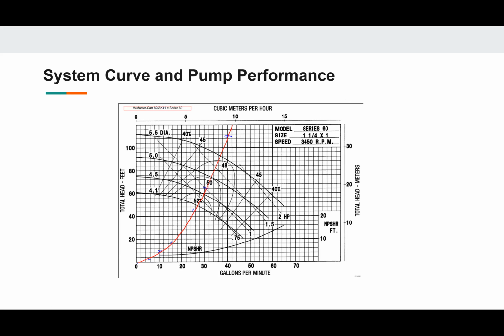But based on all the research articles published and comparisons to other similar pumps out there, we found that pumps usually have low efficiency for low flow rates and have higher efficiencies for high flow rates, like 100 gallons per minute and above. So we selected this pump based on the fact that it has efficiencies within the 50% margin.